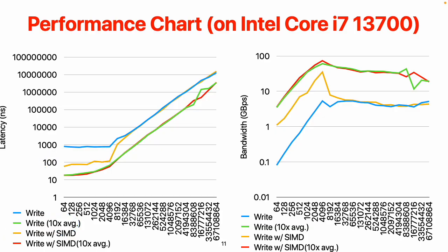So that tells you we pretty much minimize the per read latency in this way, right? But it also means that we are moving more data at the same time. Initially the latency doesn't increase because the main overhead is coming from the page fault and row buffering.